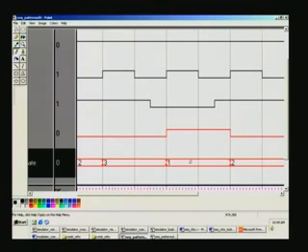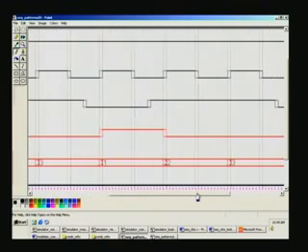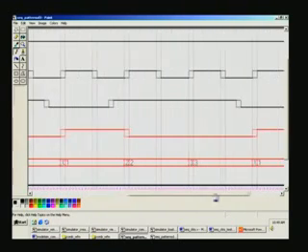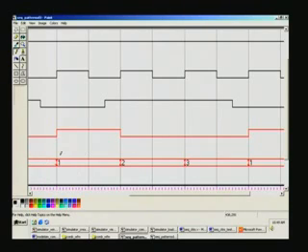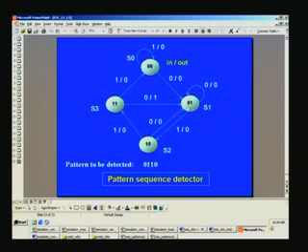Right. So next, we have already gone from third state to state 1, and now let us see state 1, 2, and 1 here. So for state 1, what is it that we are looking into? So it is 1 here. This is input here. For the earlier thing, we had sensed this as 0. Now here at the next positive edge only you have to see. So now you will be sensing 1 for the input in state 1. So let us have a look. In state 1, if it is 1, it should take you to S2 here.